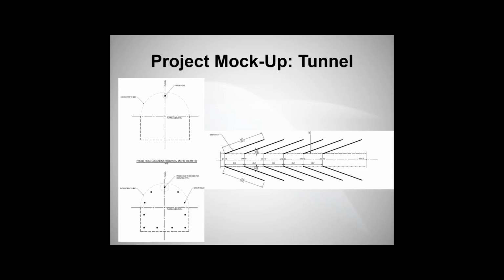And so one of the things, when you're probing, and this is just a personal pet peeve: I don't like the idea of just probing out in front of the heading in a horizontal line, because really now you're paying for drilling twice. If you're going to probe out ahead of your excavation, you might as well make the hole worthwhile. If you know how you're ultimately going to grout it, then choose a probe hole that fits in with that scheme, and so you can make that beneficial. And so this is what we did, and we provided a plan and profile to where the contractor knows that grouting and probing ahead is going to be in a fan style arrangement.